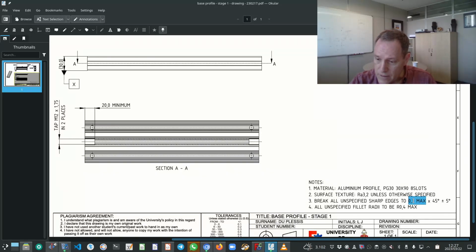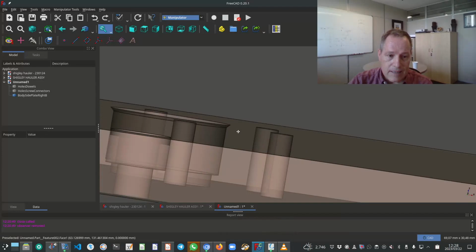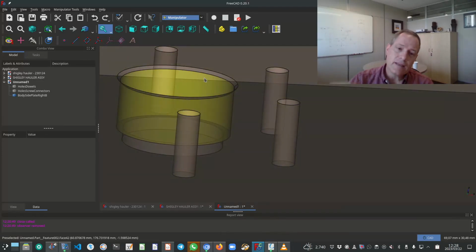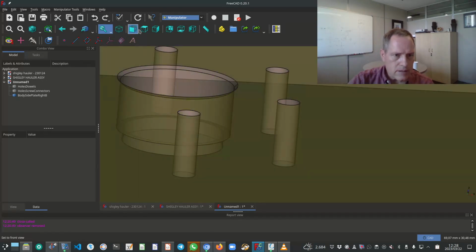I didn't specify a tolerance here, but for your chamfer you will measure the distance and say, it is whatever the distance is, plus minus a tolerance, by 45 degrees plus minus a tolerance. Plus minus 5 degrees for that angular tolerance is fine. You will understand the reason for the chamfer in a later practicum. I just wanted to point out that that is the chamfer.